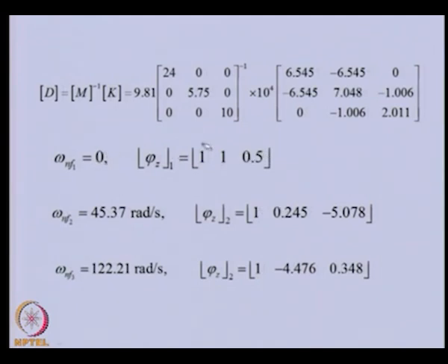You can see that nodes 1 and 2 have the same displacement. This corresponds to node 4, which is half because of the gear ratio. Otherwise, this is a rigid body mode, but these are flexible modes, and so we have 3 natural frequencies.